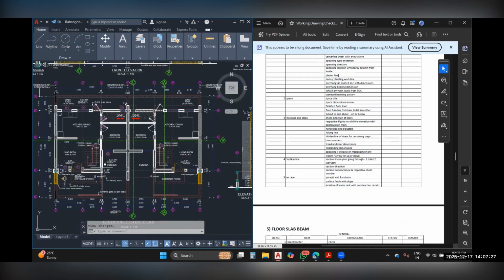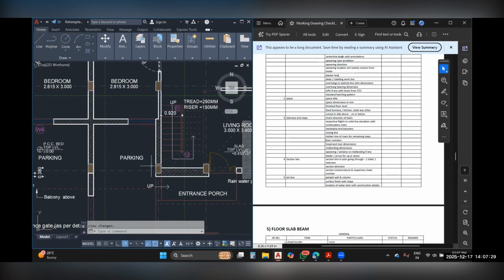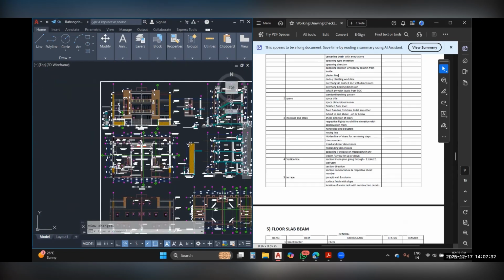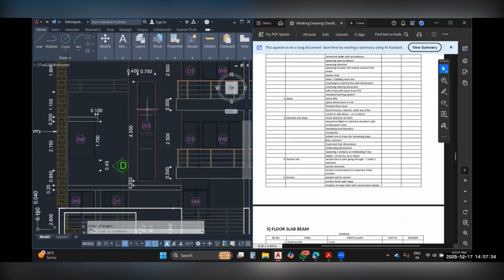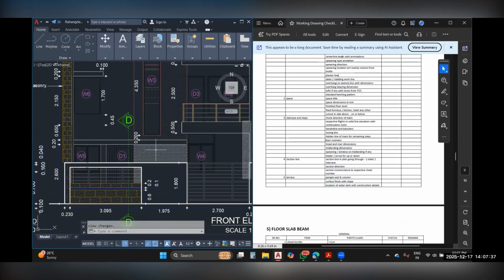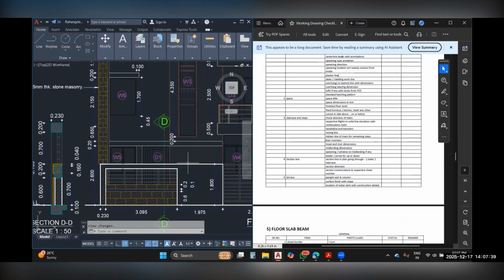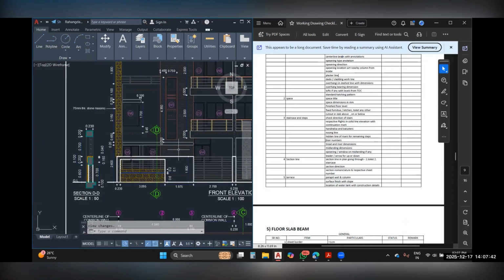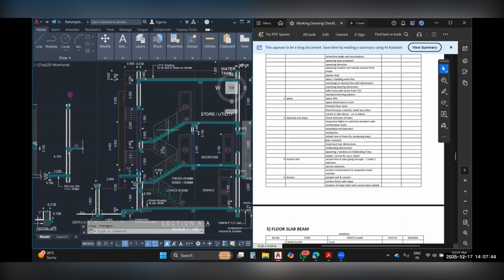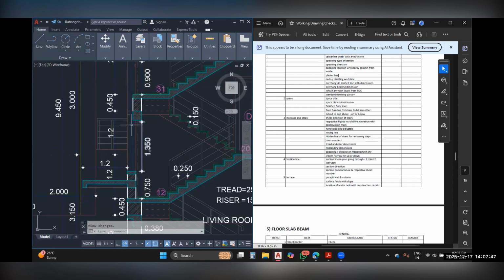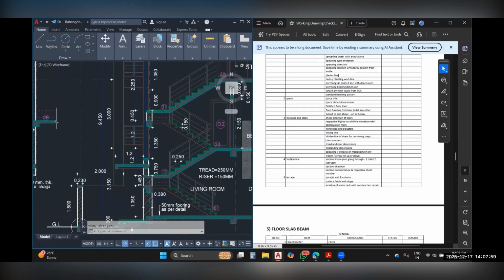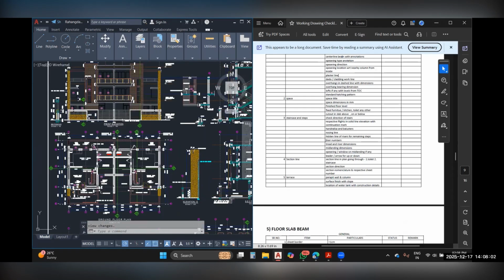Over here, there is also no opening, but in section, you could see that this is the elevation. Now that particular plan has been cut just above the sill level. But in section, you can very well see that there is an opening into the staircase. That can be verified from the section and elevation. So you need to constantly keep in coordination with the section and elevation.